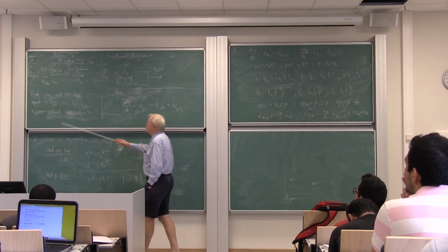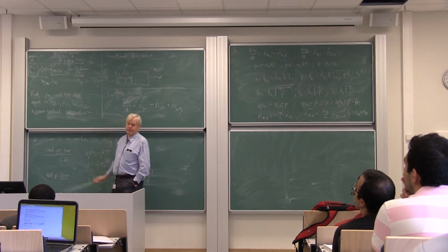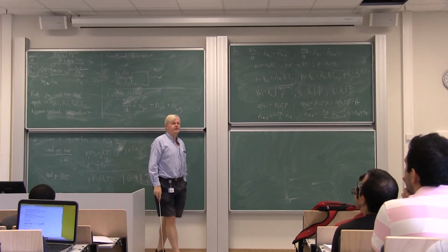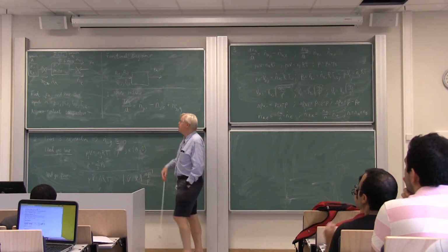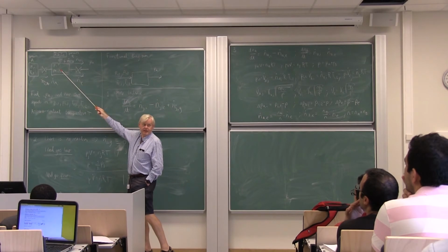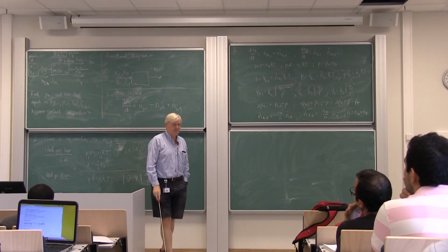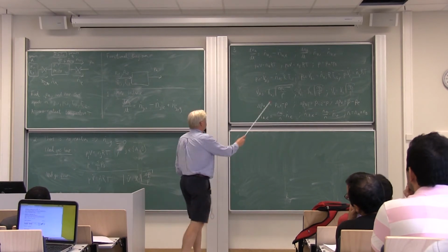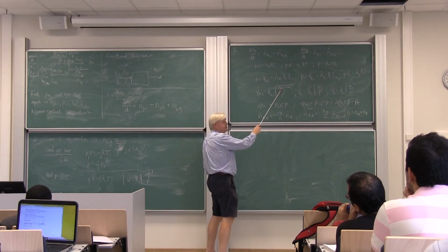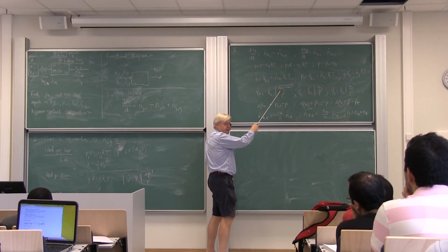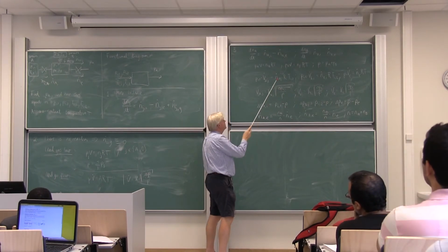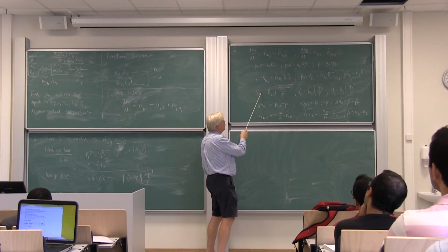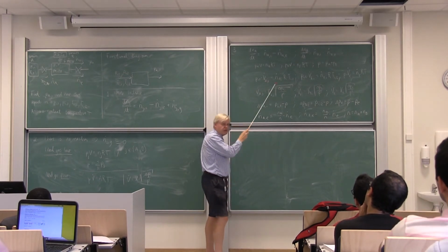What happens if the pressure in one of these tanks suddenly drops substantially so that it drops below the pressure in this tank? What will then happen? Then the flow direction changes, and then our model doesn't work anymore, because this definition of the pressure difference assumes that the pressure at the inlet is higher. If it suddenly becomes lower, this is actually a flow out of the system. So we have to change sign.